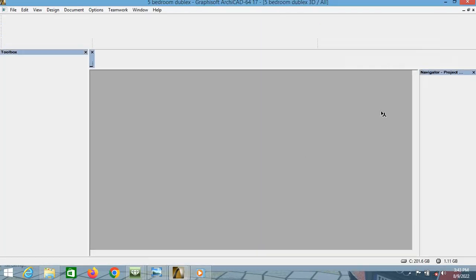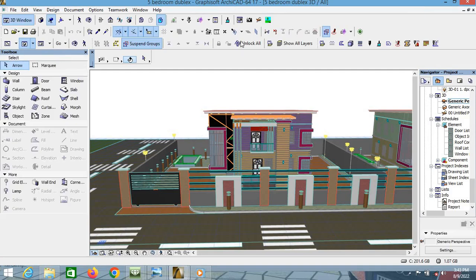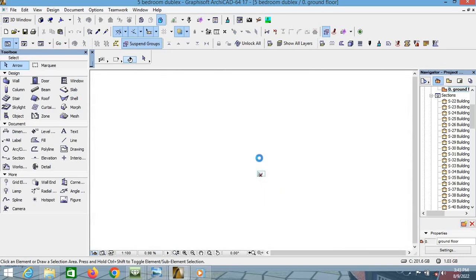I have a tweak I normally apply, and in that tweak, I do carry out my window to window and door to door dimensioning separately. I then carry out my wall to wall dimensioning separately before coming to carry out, should I say, the total dimensioning of the perimeter.